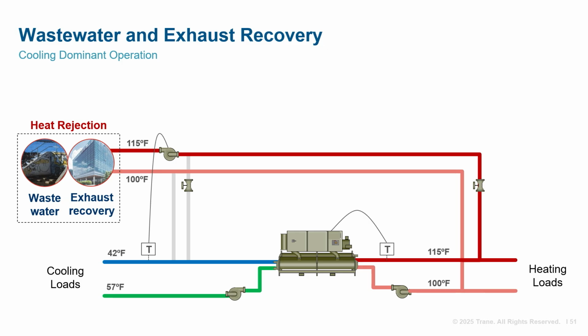Systems that operate in both heating dominant and cooling dominant modes may include valves to switch between heat recovery and heat rejection. Once the valves are switched into heat rejection mode, we've got another choice to make. What should control hot water temperature and what should control chilled water temperature? One option is to leave the controller assignments the same as in heating dominant mode, meaning that the heat pump controls hot water temperature and the heat rejection capacity trims the chilled water temperature.